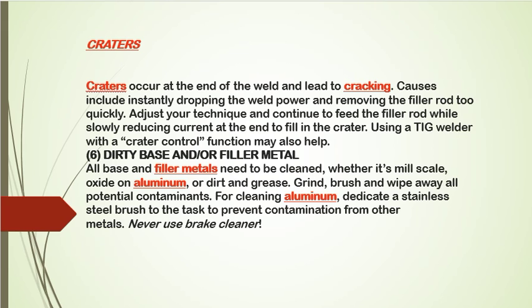You can always see it, and if it is there, then it will lead to cracking. Causes include instantly dropping the weld power and removing the filler rod too quickly. So if you're welding and the weld power is suddenly lowered, it can cause craters. If you're welding and suddenly remove the filler rod quickly, then it causes craters.